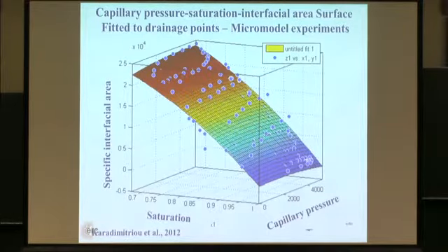In this case, we did it with micromodels, and we used image analysis to determine the area of interfaces and saturation. There is also work done where, while this was a 2D porous medium we had, people take a 3D porous medium soil sample and use CT scanning to determine the distribution of phases, and from image analysis they again calculate saturation and interfacial area.